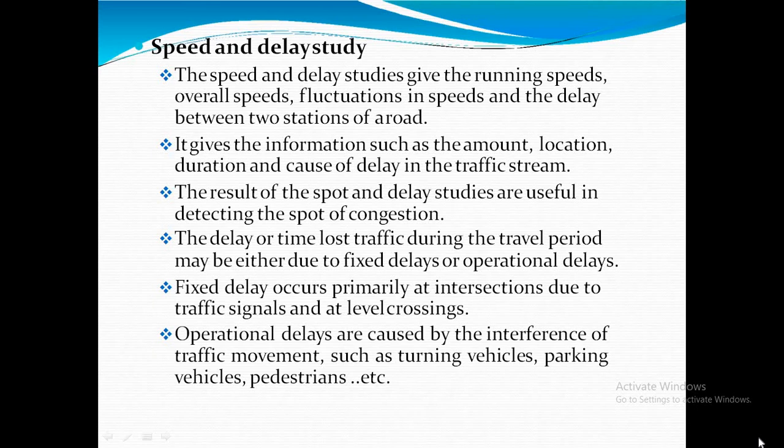The results of the speed and delay studies are useful in detecting the spots of congestion. Fixed delay occurs primarily at intersections due to traffic signals and level crossings here.